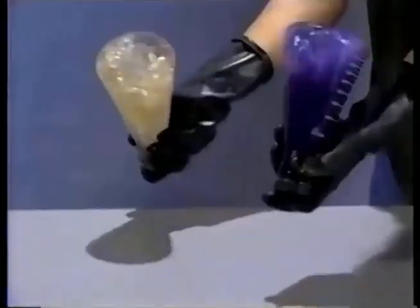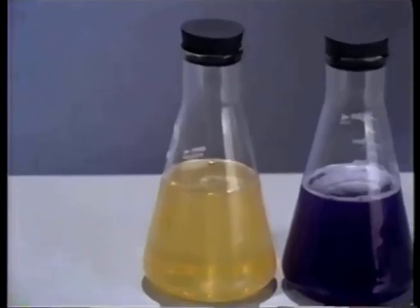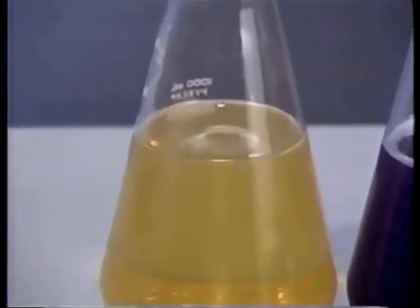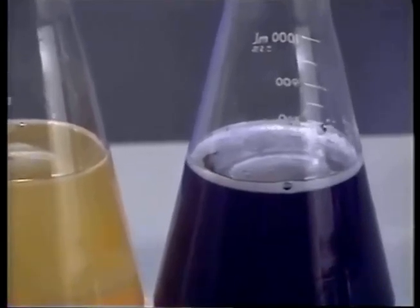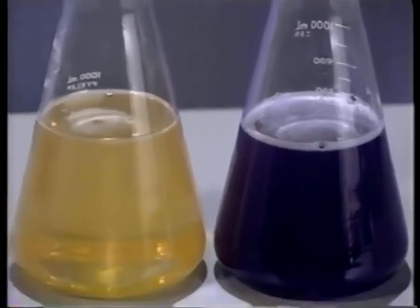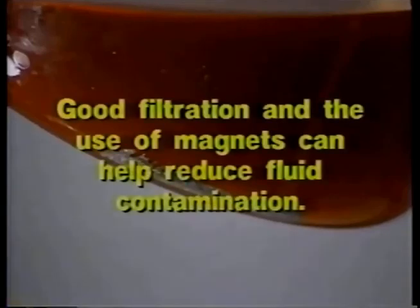In addition, synthetic fluids, like water-based fluids, have a tendency to retain air bubbles and to foam much more than petroleum fluids. To reduce this problem, most systems using fire-resistant fluids have large reservoirs to allow plenty of time for air to escape from the fluid. Synthetic fluids and water-based fluids also tend to trap and hold dirt longer than petroleum fluids. Good filtration and the use of magnets can help reduce fluid contamination.